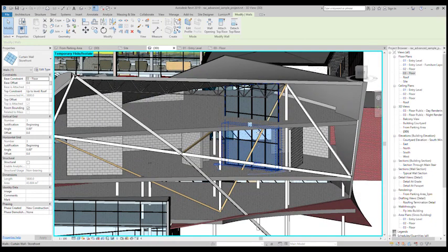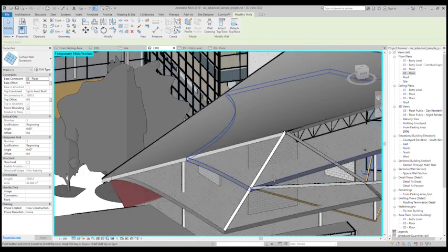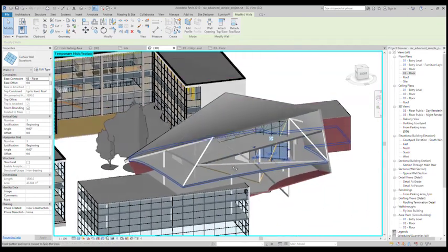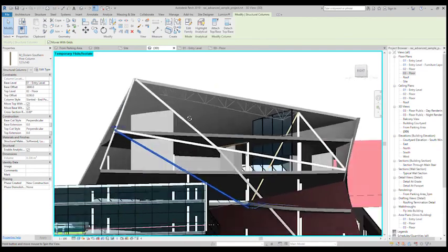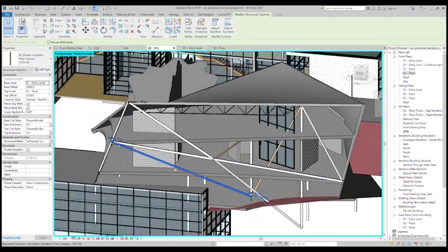It's going to be a three-part. So the next one, just going to talk about beam systems. Now that's one way of doing your adaptive components, but doing it inside your Revit project. So it's definitely not a replacement for adaptive components. This is very important. Okay, beam systems can only be applied to straight faces, and it can also only be used with existing loaded columns. It can't be complex families for the third years, like I've shown you guys with adaptive components.